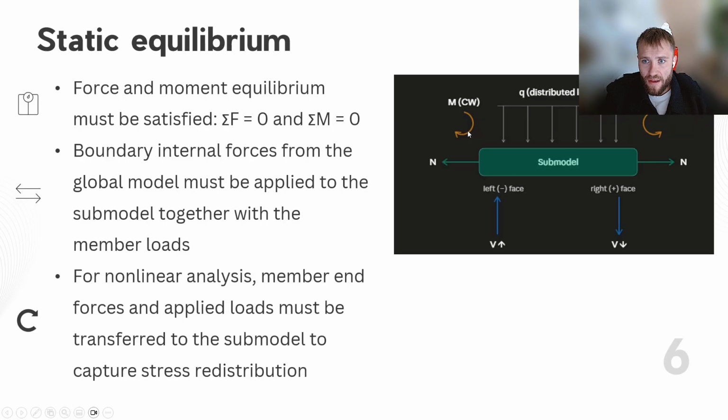There are some essential and important prerequisites that you need to take into account. One of them is that we are solving a statical structure, a structure that is basically static. There are no dynamic forces, and the structure needs to stay in place. So there needs to be what is called a static equilibrium. It means that forces and moments must satisfy the conditions that the sum of the forces in all directions has to be equal to zero, and the sum of the moments has to be equal to zero as well, so the model stays in one place, not in motion.